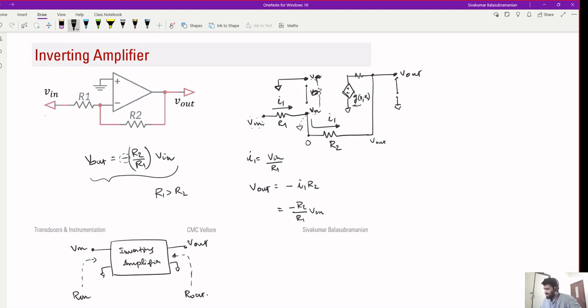In general, if you have a two-port network like this, how do you find the input impedance? Output side, sir, we are using open circuit voltage, short circuit current for the input side. Right, so that's okay. So in that case, what would be the output impedance in this case? If you look at this, the voltage is being produced by this, so even if you short it, this voltage source will maintain that voltage across the short. So here, your output impedance would be 0.